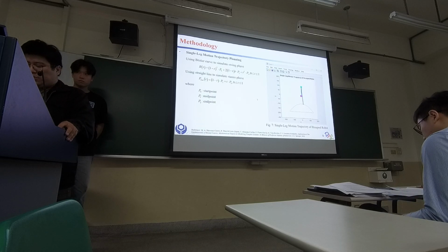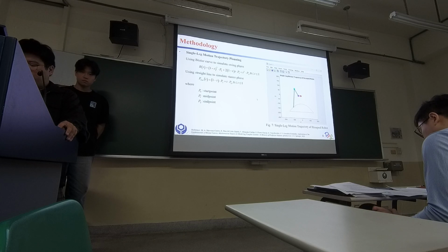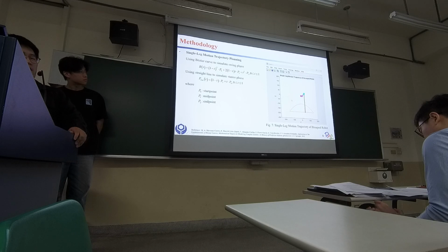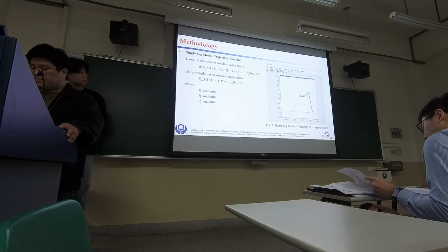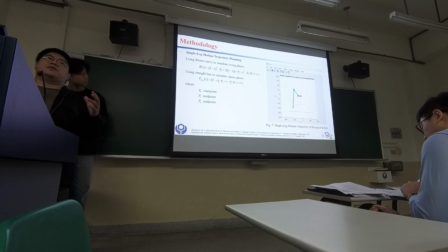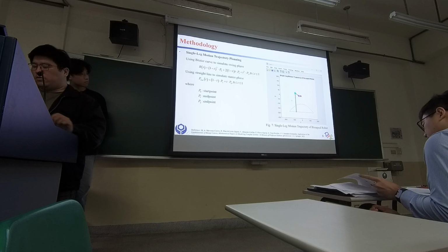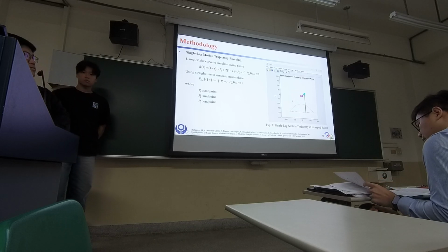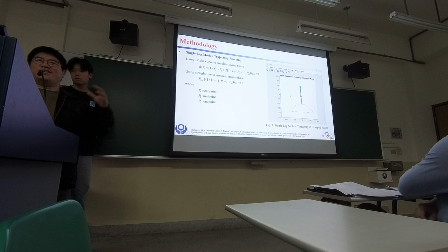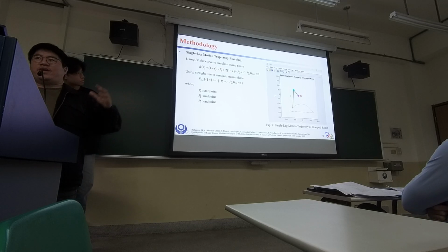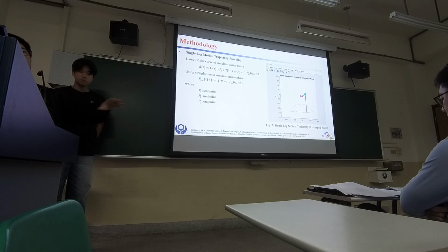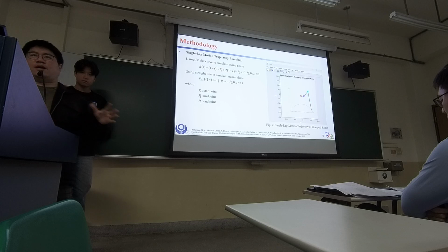So next we have an ideal trajectory of the end effector of the leg. As you can see, the animation has been simulated. This will serve as our target for our following prototypes. So next we will check our single leg model to see if it matches the trajectory, and after verifying on one leg, we will duplicate the result on the other 5 legs.